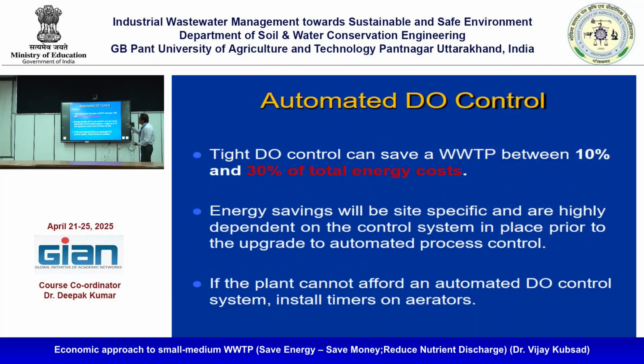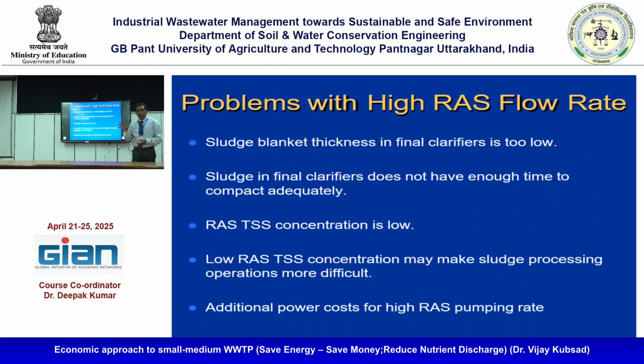So you have already seen the approximate value of reduction when you change the DO. Then there are problems with high recirculation of the sludge. You will have to see if too much sludge is coming up and if it is not active, because if the bacterial health and the secondary containment are not working properly, you are recirculating that again, so it will destroy, meaning more maintenance cost. So that is how.